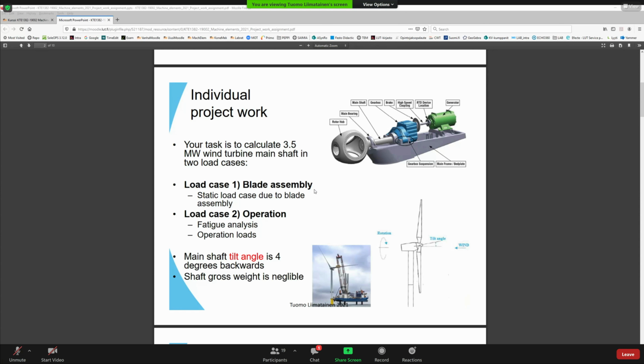The Wöhler curve is using only amplitude. But in real cases, like now in the exercise, we also have mean stress induced. And then we use the Goodman equation to modify our loading amplitude so that it will give the equivalent result when we apply only the Goodman modified amplitude onto the Wöhler curve.